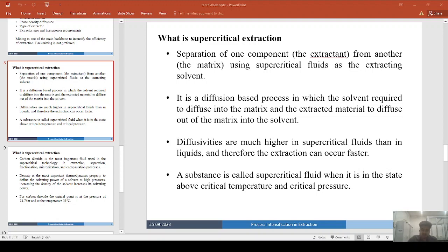The extracts of bioactive compounds can be obtained by the extraction of solid matrices such as leaves, seeds, pulps, etc., or by the extraction or fractionation of liquid mixtures, such as aqueous solutions, fish oil, microalgae oils, vegetable oil, deodorized distillates, etc. At high pressures near or above the critical point, which often involves pressure and temperature, the solvent density increases drastically, and this is the most important parameter associated with solvent extraction.